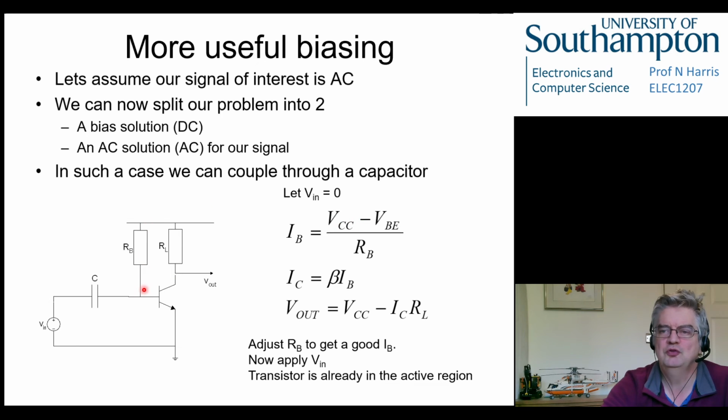So it's just the voltage drop across this resistor because there's nothing else in this path, and divide that by RB because that's the only resistance we've got there, and that defines what IB is into this transistor. We don't know what VB is, to be fair, at the moment, but that's the equation that describes what's going on there. We also know that IC equals beta IB, so the current through here is going to be beta IB.